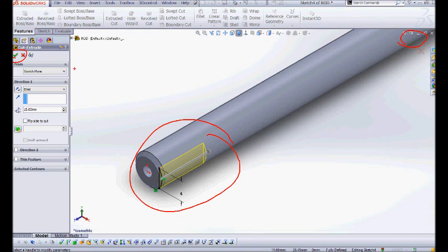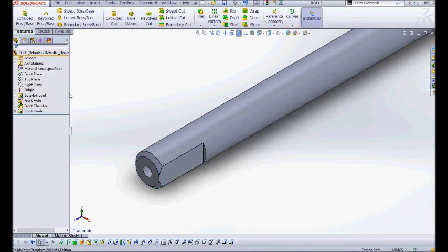You'll notice that one slash got rid of a bunch of geometry, and all I've got left is this little leg down here. To get rid of that little leg, once again I hold down my left mouse button, slash it across, and then release. That's how it works.